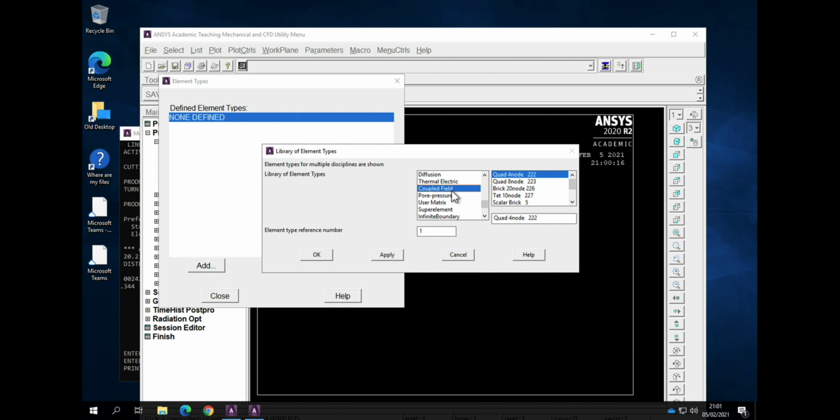So if you apply a stress to a piezoelectric, you'll get a Hookean strain based on the Young's modulus, but you also develop a voltage. And what does a piezoelectric do in response to an electric field and a voltage? It strains, so it'll offset that Hookean strain. So there's a coupling between those two.